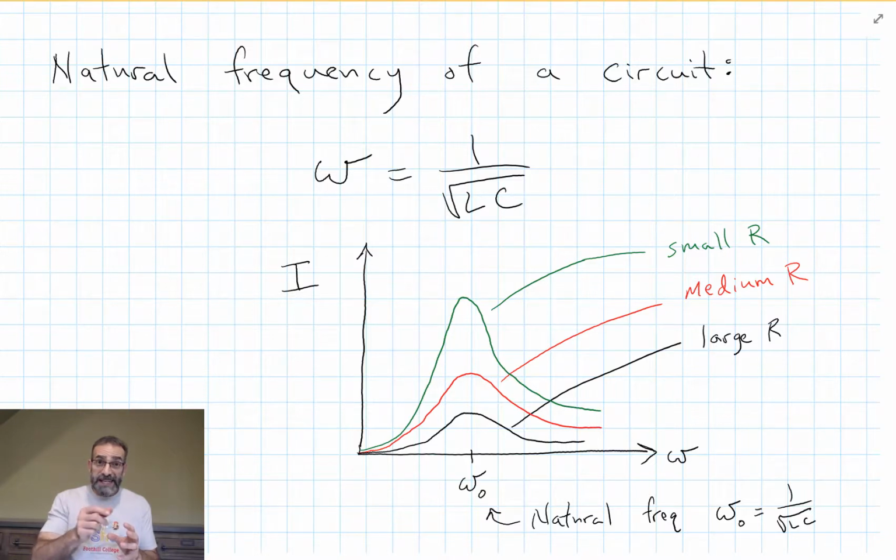That dial is connected to a capacitor that can change capacitance. And as you change the capacitance, you're changing the resonant frequency of the circuit. And whichever frequency is at the resonant frequency of the circuit, that's the one that creates a big signal in the circuit and can get amplified and sent to your speakers. That's the radio station you listen to.